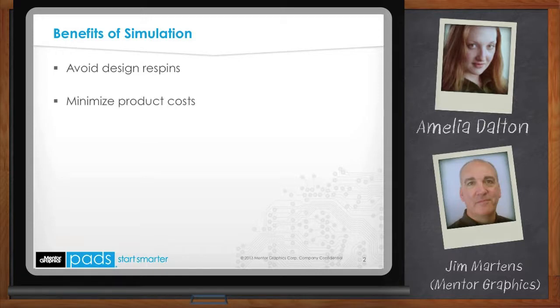Wow, okay. Virtual prototype, which is simply predicting your design's real-world behavior by using software instead of going to the test lab with a prototype, has become more mainstream because it saves both time and money. Using IC guidelines as your only source of design parameter information doesn't let you make changes or optimize your system with confidence. But if you can experiment by changing component types and content, such as reducing the need for decoupling capacitors, you can avoid designing to the maximum parameters suggested by IC guidelines. Approaches such as this can use less board space and lead to reduced layer counts, which introduce cost savings.